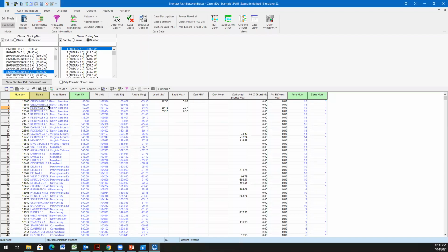New question here, and I'm not sure if I fully understand it. I'll take a stab at it and then maybe open it up to others here at PowerWorld to help with it. But the question is, is there a simple way to visualize PMU, not in a full one-line view, but rather when a user zooms to a specific part? I guess the way I would address that is to use a conditional zoom level with the object.